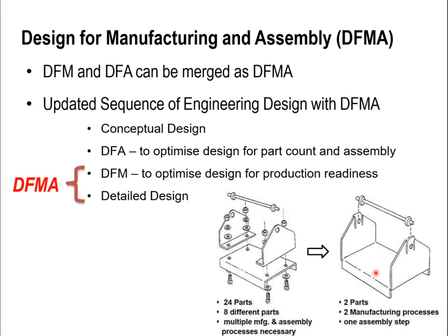Just an example. Or I can make it with sheet metal working by, instead of having the handle here, this part can simply be bent here, and then the second process is just to hold the part with a bolt or by doing, for example, spot welding.